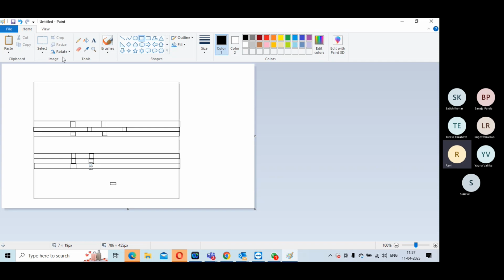Then the third part of that is the ECO-able filler cell. That is called gate array. This is also post fill. Basically, the point is it's a special cell which can be used for ECO. It will act as a filler, but you can internally convert it, just by changing the routing.